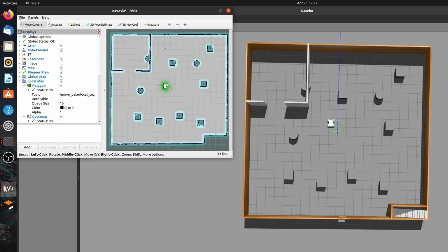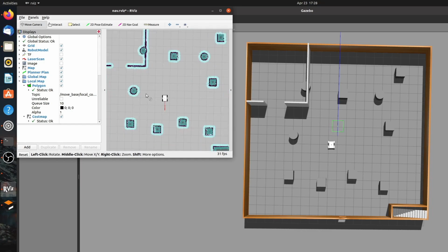These are the Monte Carlo localization. It's basically saying it thinks we're in one of these arrows. It's not very confident yet because we haven't moved anywhere. But if we set a movement goal here, we get new laser scans and compare them with our map, and it'll get more confident as it goes. You can see the cloud getting smaller. And now it knows exactly where we're at. The laser scans are matching up with the map now, so we know we're in the right spot.